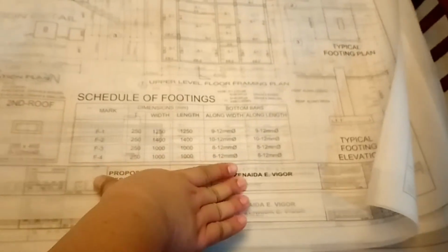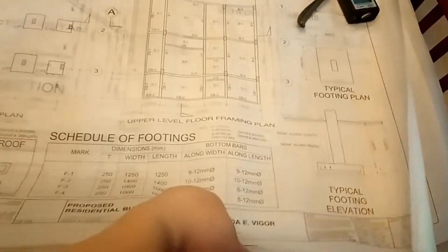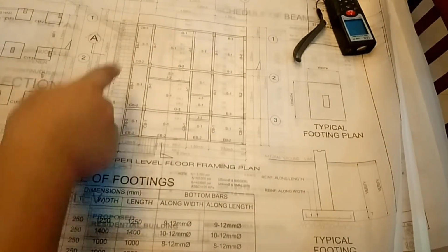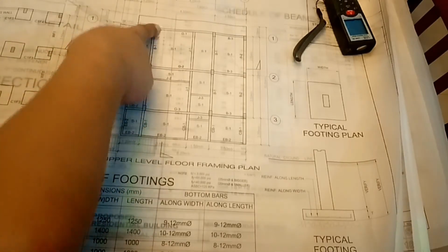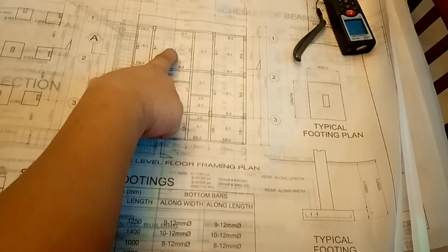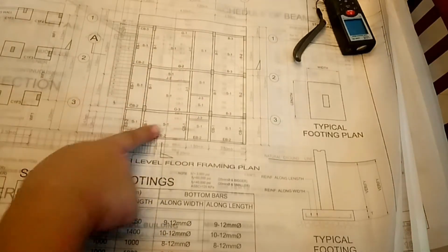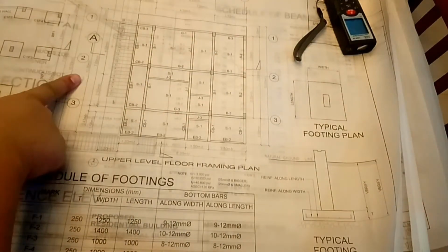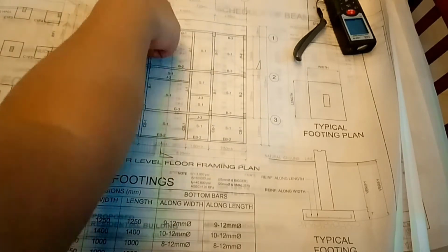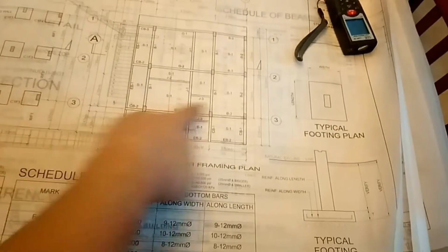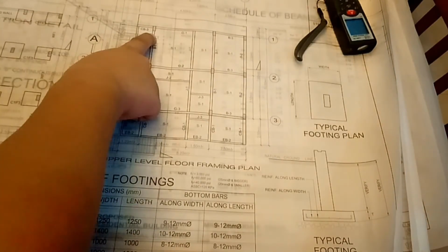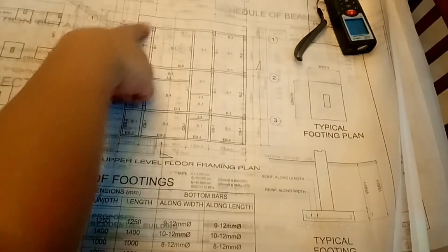You know, let's look at the upper floor framing plan. So I hope you can see this. Okay. So this is the beam 1 here. Okay. Then we have S1, meaning this is a one-way slab. So our structural engineer designed the house to use a one-way slab all throughout the entire second floor system. Okay, so you can also see the call-outs, the columns. So basically, same column here, the size is the same column size also for the upper levels.